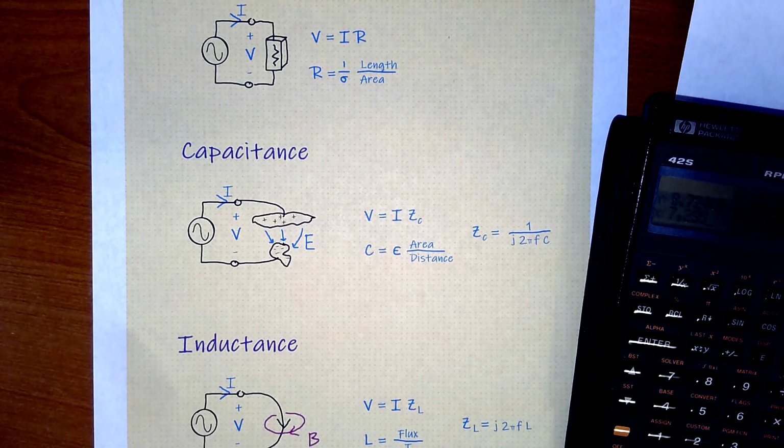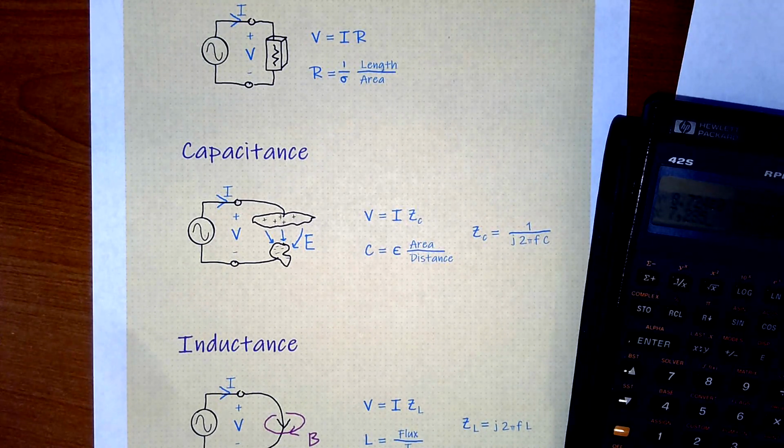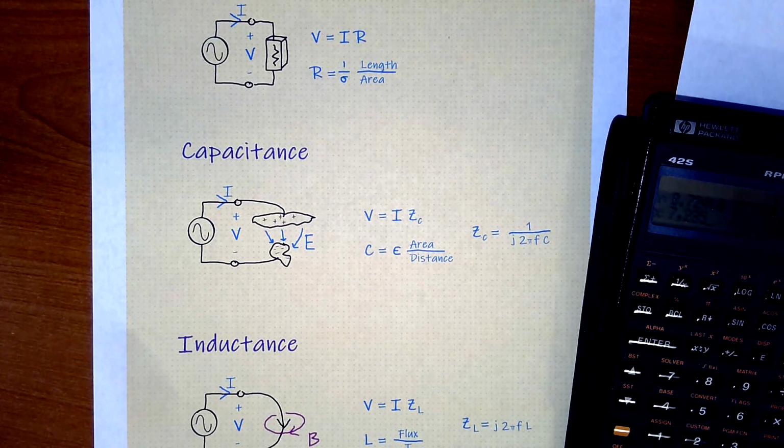So what's the bottom line? Are resistors worthless at radio frequencies? No, not at all. However, depending on the dimensions of the devices and the frequencies involved, you may have to limit yourself to using resistors from, say, 10 ohms up to a k ohm or something like that. If you've got surface mount parts, might not be a problem to go much higher than that and much lower than that. But you can't have arbitrary values.